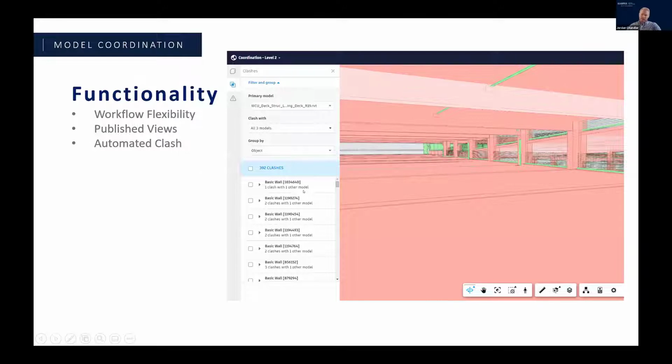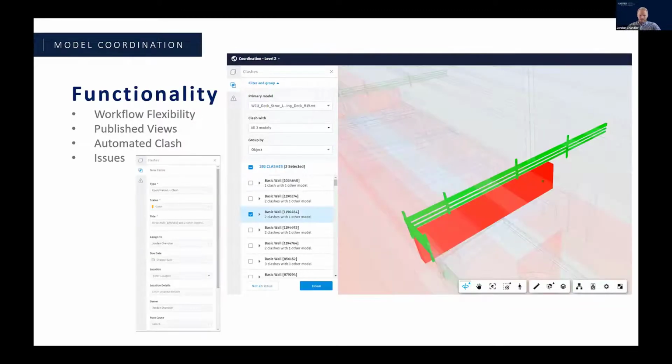And if you've ever had a piece of ductwork running through a floor joist or a truss or something, and that joist is made up of 17 different steel elements, you get your 17 clashes for the duct, and then 17 clashes for the insulation, and then the hanger, and so on and so forth. This kind of cuts down that process, just automatically groups that for you. I think Ava was saying using some of the features in Navisworks to kind of group those clashes. This kind of takes that step out of the process. So that's something that we definitely found pretty valuable.